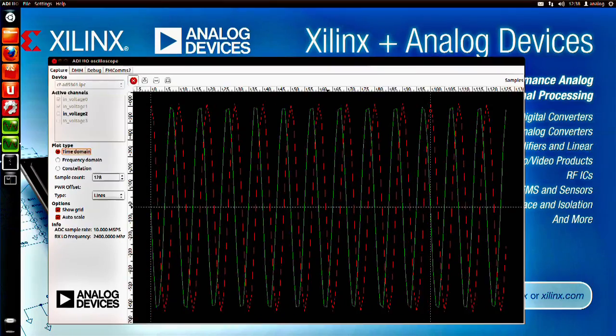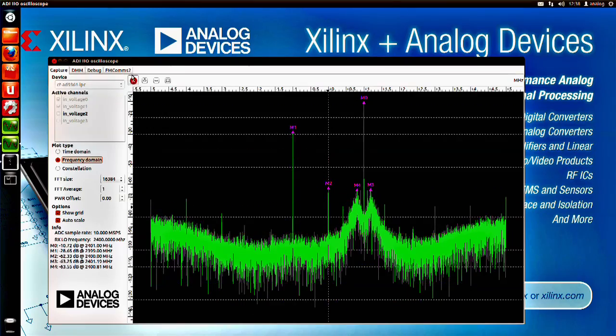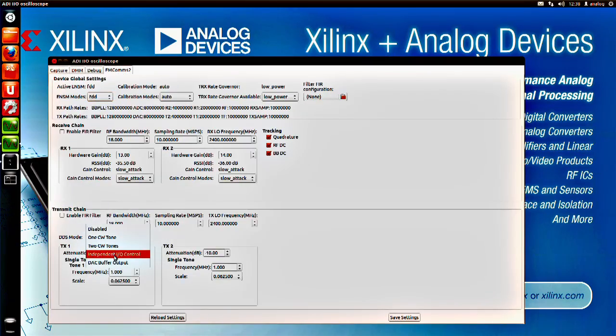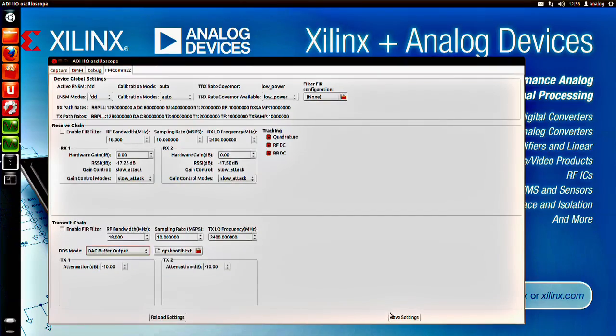What we are looking at is the output of ADI's HDMI transmitter, the ADV7511 found on the ZC706. Here the system is booting and we can see the Linux Industrial Input-Output, or IIO, oscilloscope application being shown. This is the data on the receive side of the selected channels.